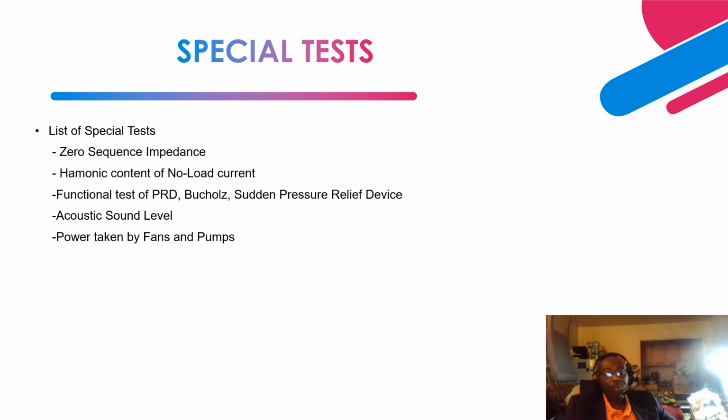Both have to see the fault before the sudden pressure relay will activate. Most often than not, the sudden pressure relay device is integrated to an auxiliary device, 64X. From the 64X, it goes to a lockout relay, and from the lockout relay, it trips the trip coil of the main breaker.